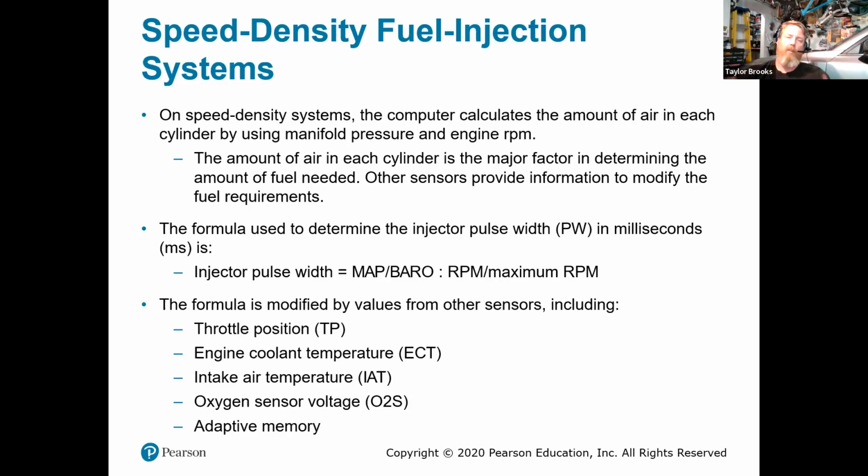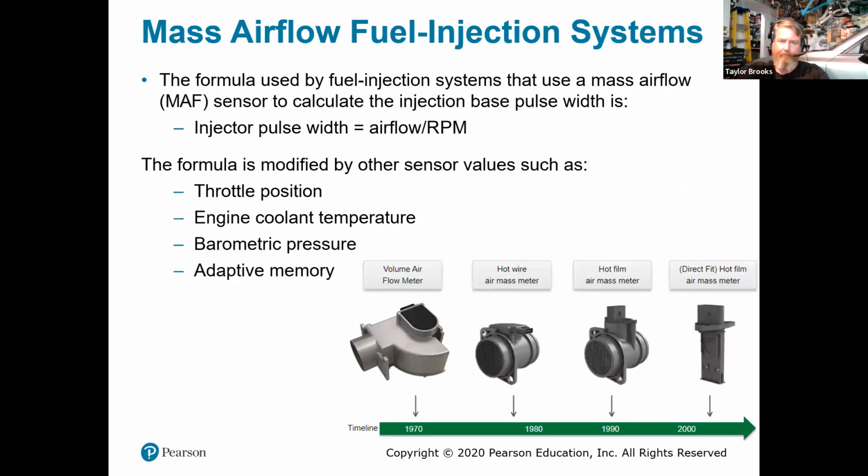Pre-detonation, again, is one of the things that we're trying to avoid, otherwise known as knock. If we're getting into where we have a pre-ignition knock, you will start to do damage to internal components of the engine, typically the piston because it's weakest, because it's made of aluminum.